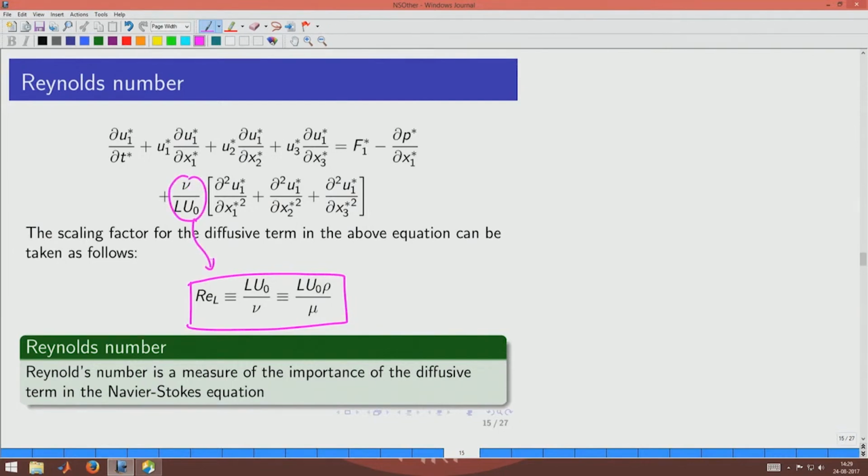So, you could see that Reynolds number is naturally coming out of the Navier Stokes equation as a scaling factor in front of the diffusive term, and the units are wiped off because the non-dimensionalization is done for all the terms. Now, it is also basically characterizing the problem, because we saw that it comes out of choosing the length scales and time scales and velocity scales to characterize the problem. So, Reynolds number actually is characterizing the Navier Stokes equation for a given problem.